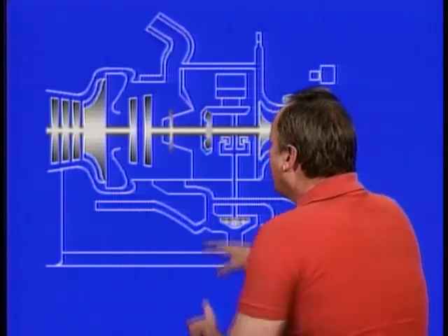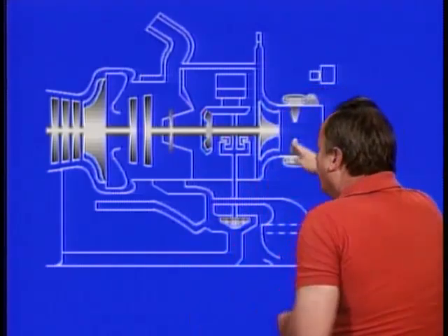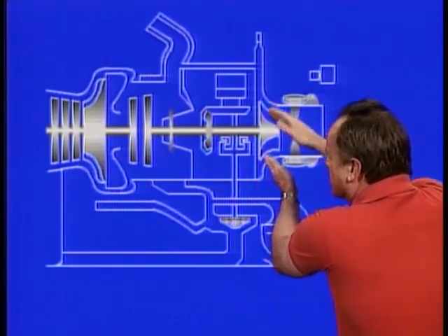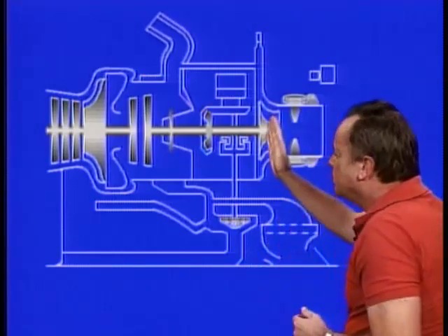Let's assume you have a change in the electrical load. How can you regulate the pneumatic load? Well, they do that with inlet guide vanes to this load compressor, and you can change the amount of air that gets to the compressor.